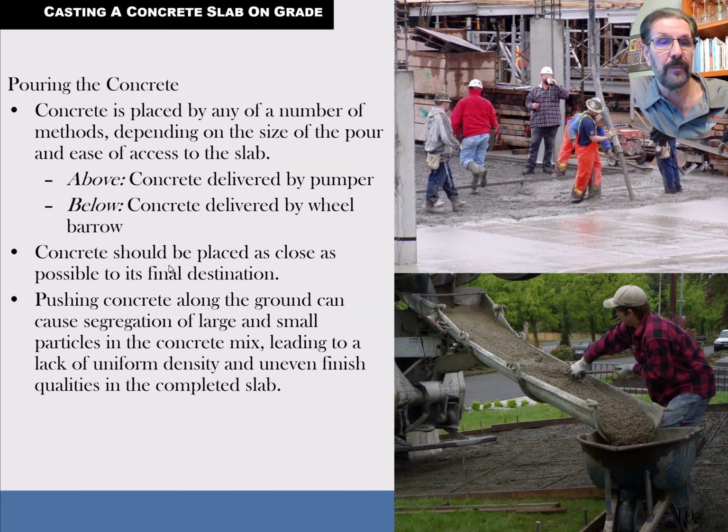Okay, I digress. You're also not supposed to let concrete drop very far. If it's coming out of a concrete chute in the back of a ready-mix truck, like this bottom right-hand picture, you don't want it to drop too far: no more than 4 feet maximum. Same thing when it's coming out of the snorkel of a concrete pump.